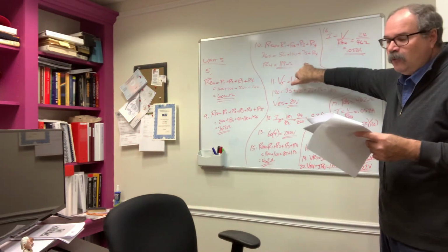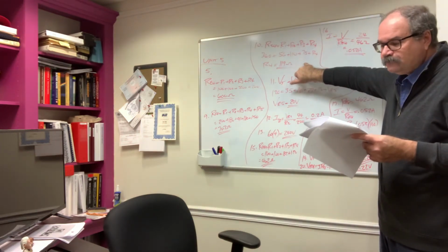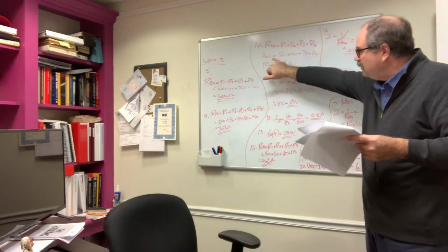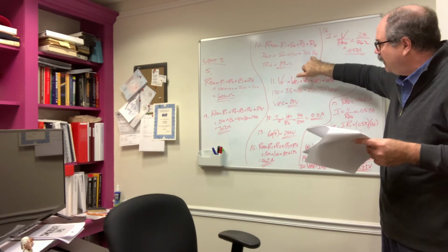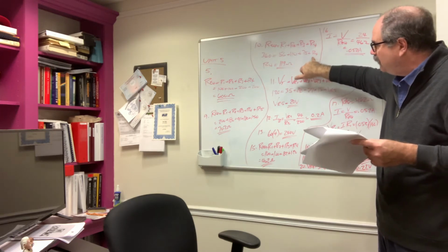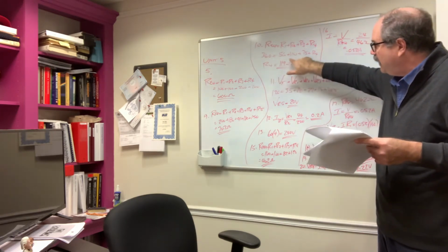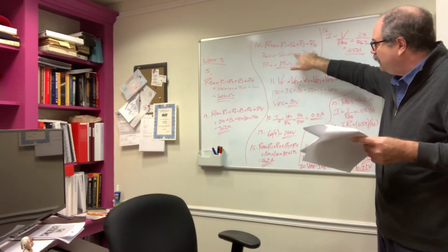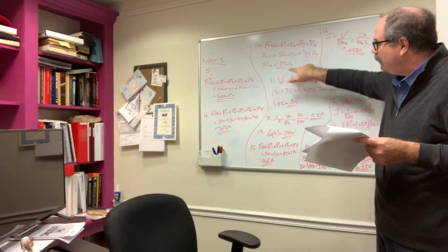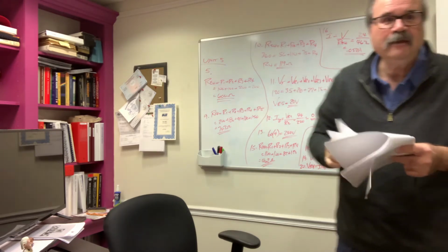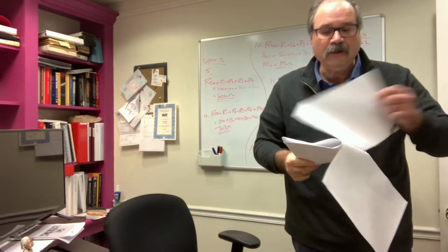So what we're doing in this example, we're given the total resistance of that equivalent value of 360, and we're being asked to solve for the 4th value of resistance. So 360 is equal to R1 plus R2 plus R3 plus R4. Plug the numbers in, solve for R4. R4 is equal to 119 ohms.